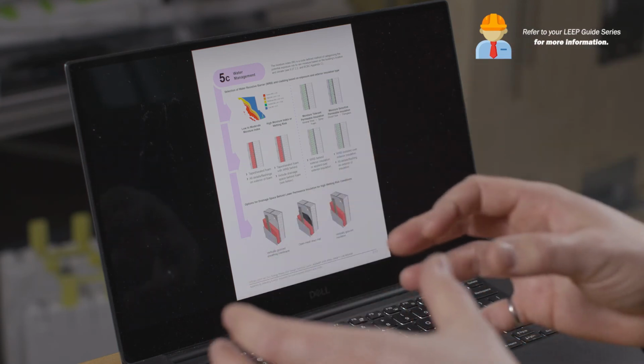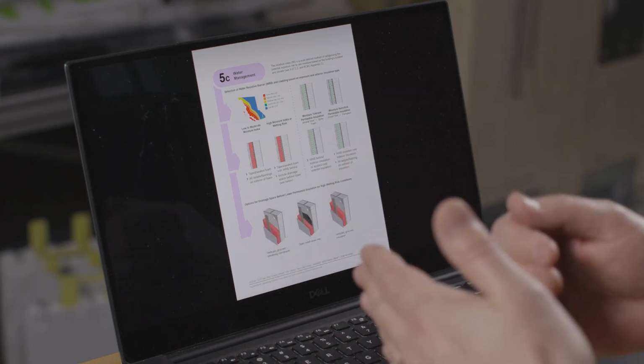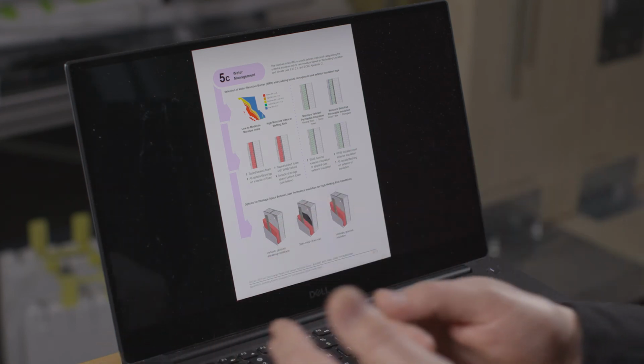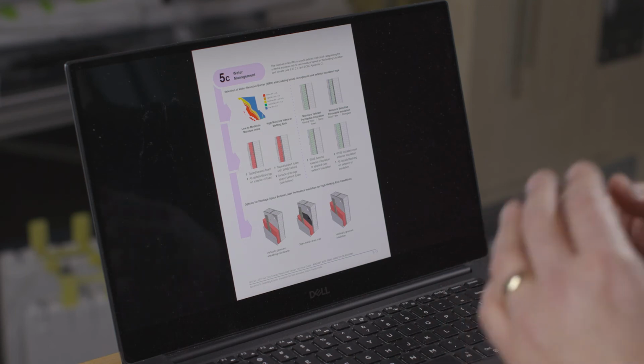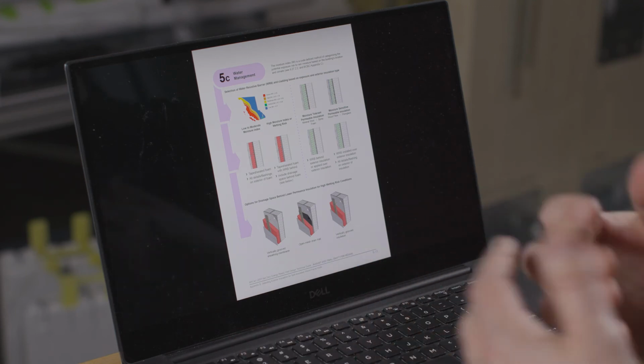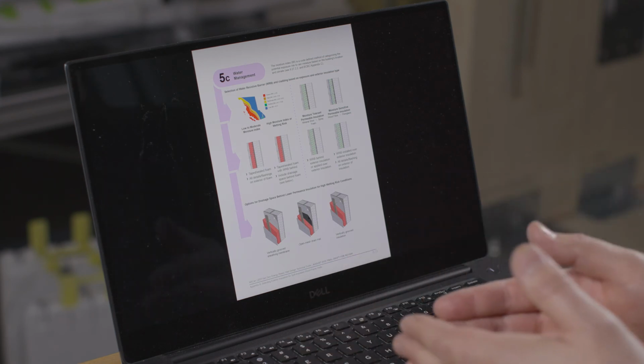The third thing that gets looked at is water management. Okay, so water management, you've got your assembly, you've got the exterior insulation, you got some thickness of exterior insulation. Then what do I do for water control? What's the best thing I could do? Okay, and what's going to drive this is where you are. Are you in a wet region of the country? Are you in an area with a high moisture index? And if you're in an area with a high moisture index, you need to take a bit more conservative approach